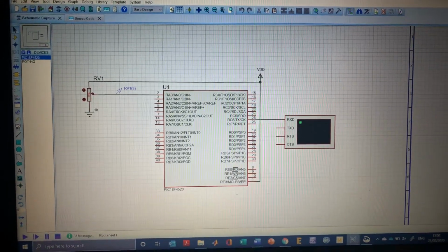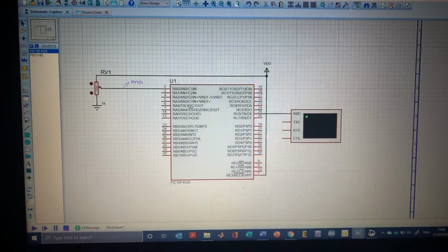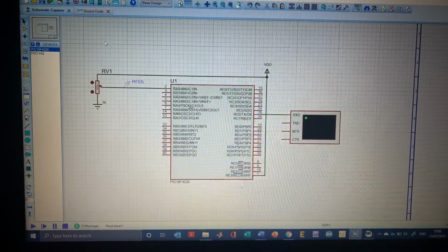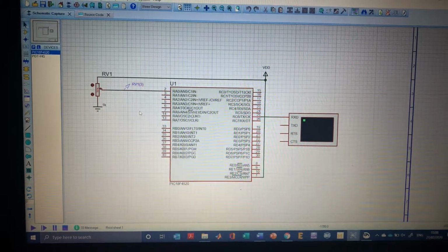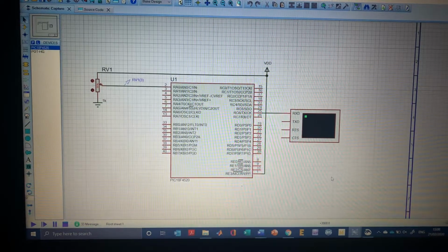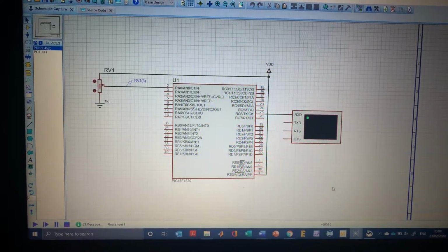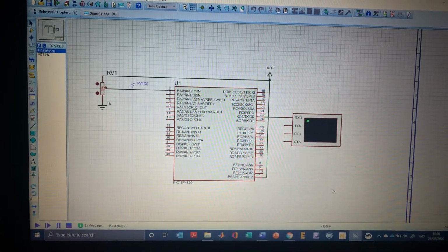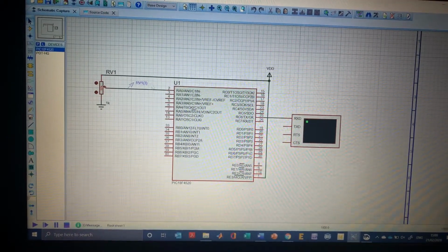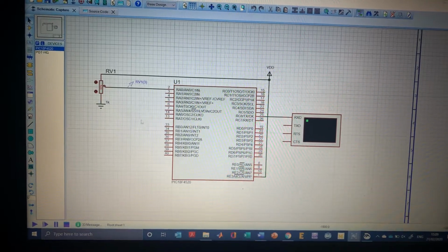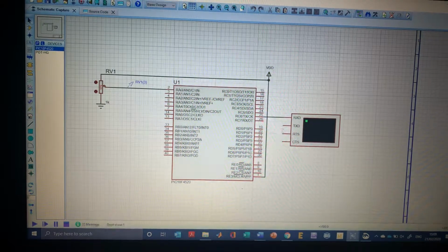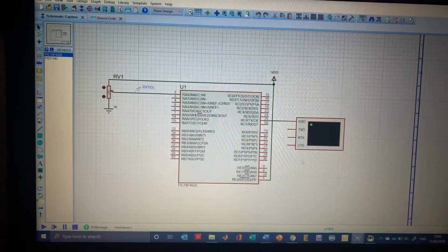This is week 4 lab 2 exercise, in which we are using a USART library to produce a two-way communication, and we're using special purpose pins at port C, which are known as TX for transmission and RX for receiving information. We are converting an analog to digital signal provided at A0, and then sending it to port C for transmission to see the output on the virtual terminal.